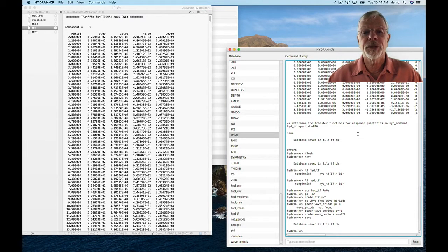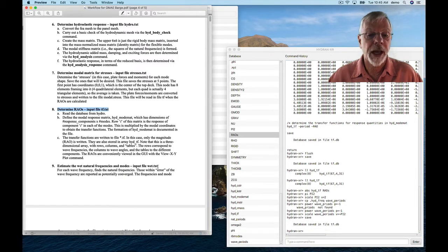Okay, so that finishes this video. We've covered how to calculate transfer functions. The transfer functions for forces and stresses take some investigating into the command reference, looking at the different element help files and or help commands, and understanding what are the responses that are available to calculate. So with that, we'll terminate this video. And the next video, I believe, if we come to the workflow document, is how to estimate the wet natural periods and their natural frequencies and the wet modes, if you will.